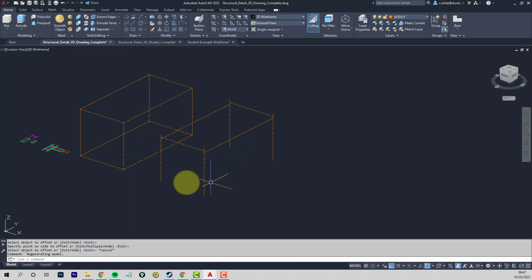Okay, so hopefully you understand the difference between those two. This little model's okay, but this is more accurate because the beam center lines are in the right positions, and that's going to affect the structural reactions and the answers that come out of the system.